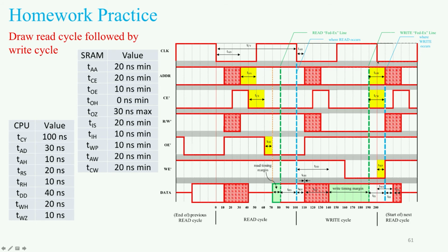So the clock fell here. And the falling of the clock tells the CPU that it needs to get that data off of the bus, and it begins the transition right here. Okay, so it begins the transition here when the clock falls, and then the data is going to be held for 20 nanoseconds because the write hold time was specified as 20 nanoseconds. And oh, look at that, it just happens to work out, right? So the data is held valid for 20 nanoseconds after the falling edge of the clock,